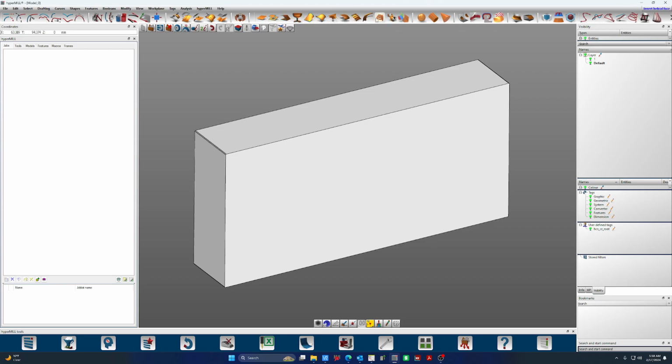From here on out, we're going to see some different ones. Helical face and blending are not tools I use a lot. Join can be super helpful when we have a ton of surfaces and we're really trying to unify or unite common surfaces that are tangent or have UV vectors that are all driving in the same direction. Instead of clicking 5 surfaces, we just want to click this one large surface. It's only going to let us connect surfaces that are tangent, that do have similar UV vectors.